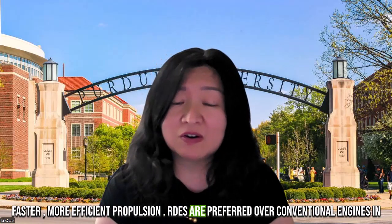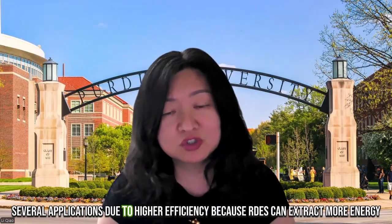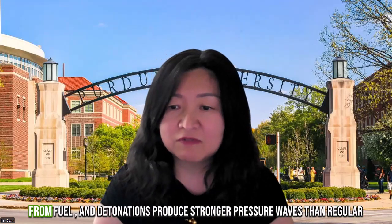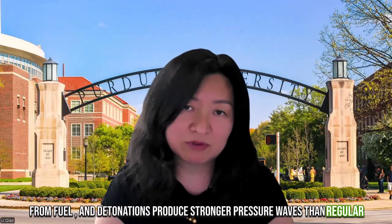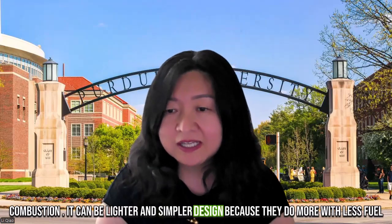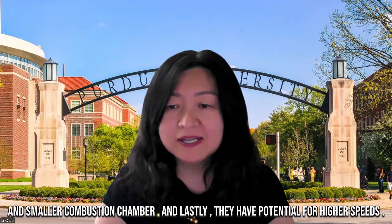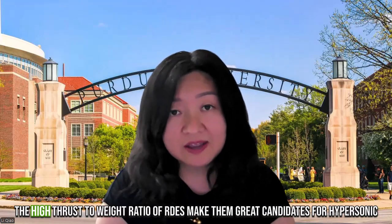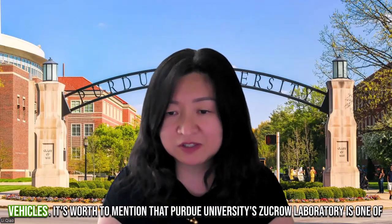Now, RDEs are preferred over conventional engines in several applications due to higher efficiency, because RDEs can extract more energy from fuel, because detonations produce stronger pressure waves than regular combustion. And they can be lighter and simpler in design because they do more with less fuel and a smaller combustion chamber. And lastly, potential for higher speeds. The high thrust to weight ratio of RDEs makes them a great candidate for hypersonic vehicles.